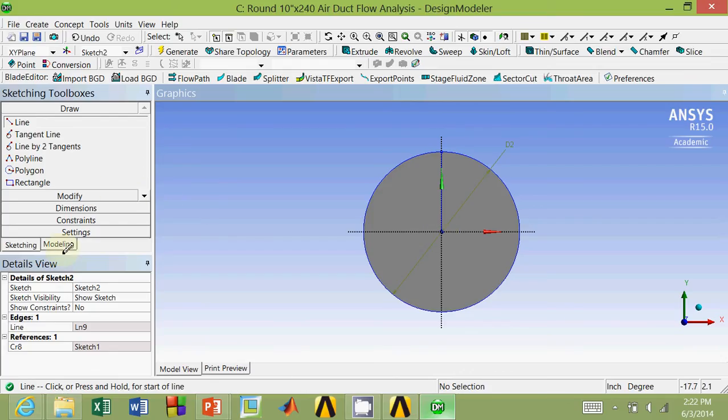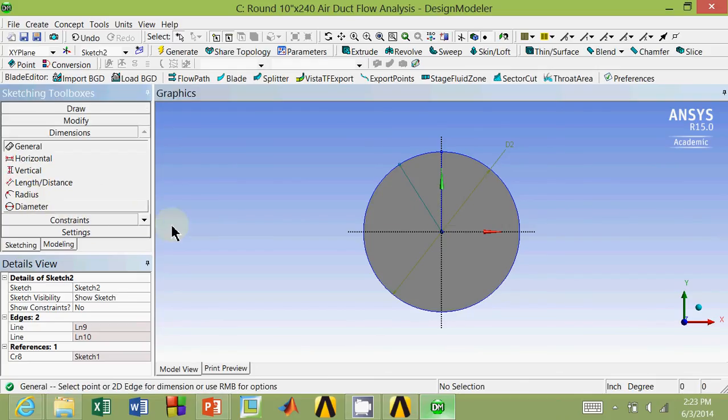So I'm actually going to click the origin again, and then out to the circle. See, right now it doesn't know. I don't know if this is 3 degrees or not. I know it's going to be a lot bigger than 3 degrees. So I can dimension this. If I go down there, it'll be an angle.